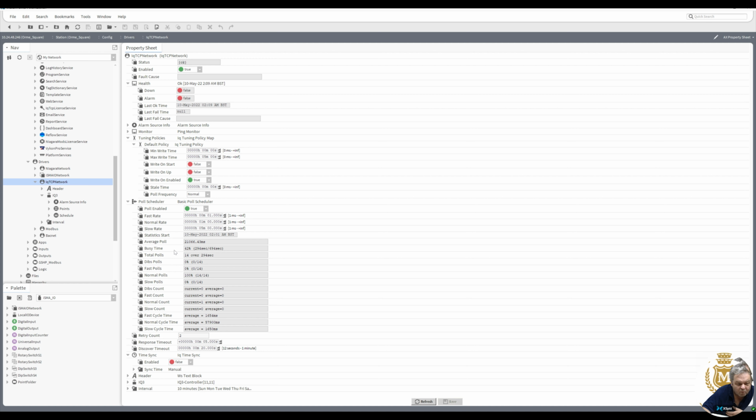When you're talking busy time, be it Trend network or Modbus, or BACnet, my rule of thumb is not to take it over 75%. Always have it 75% or less. You don't want to be seeing 99% there. Anything below 75% you should be happy with, and that could be the Modbus network, the BACnet network, or Trend network. So I'm happy with that at 42%.